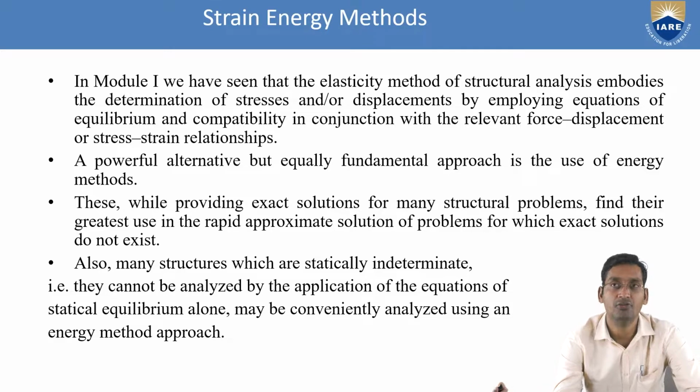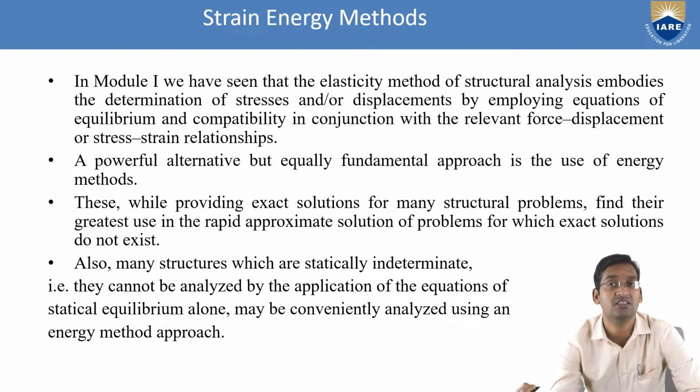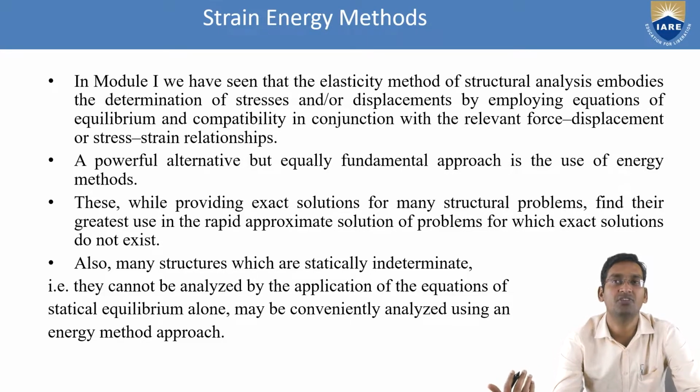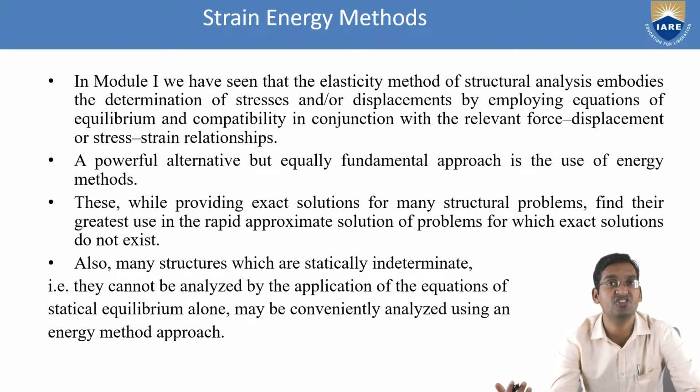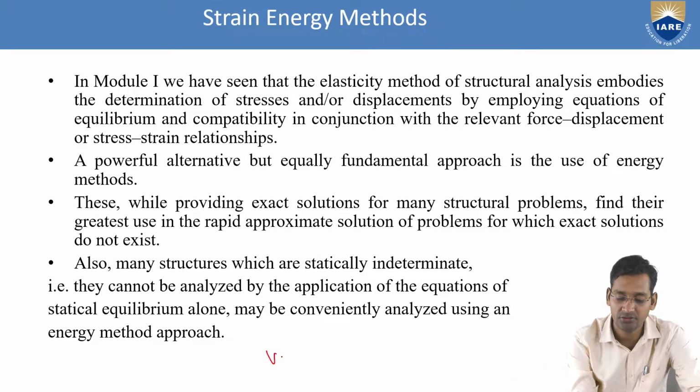Meaning, where the first module fails to analyze, that analytical method or just a formula like PL by AE, there it fails. By using this method we can find that type of problem also. By name itself it is the energy method. So we will find how much energy is absorbed by that body, and because of that energy, the work done is force into displacement. Once we have the energy, then we can see. Simply you can say work done is force into displacement.